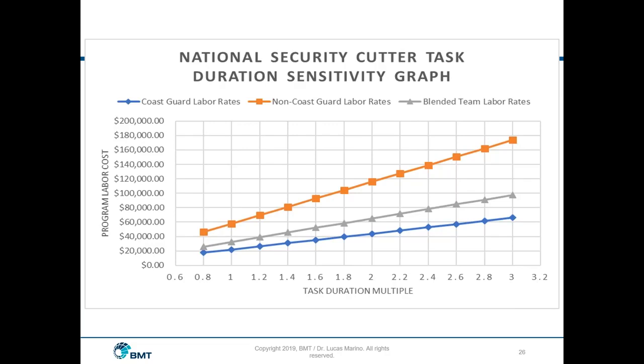The higher risk was in the cost of tasks taking much longer, because the trend was going toward longer maintenance tasks as the life cycle drew on, because we started to find more interferences. And you know what? These bolts are getting weak and breaking because of age and heat and cold and heat and cold, right? So as we went through the life cycle of the asset, what we found was task durations were sometimes up to 3 times what we had prescribed they should be, okay?